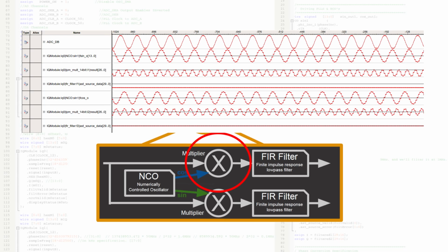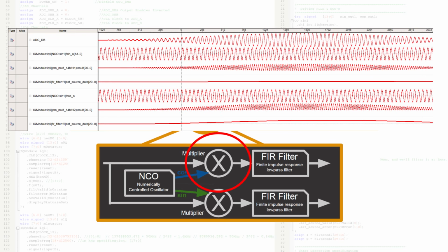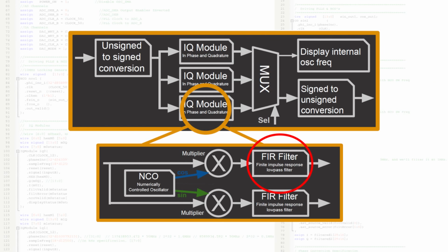The important thing to note here is that the output, both the DC as well as the doubled carrier frequency, still contain the amplitude data of the original input signal. When there's amplitude modulation on top of a DC signal, this just gives you the signal back at some DC offset. This is why this signal is very useful for us, and why we don't care so much about the signal with the double carrier frequency. It's in our interests at this point to filter out this higher frequency that we don't want anymore, and just retain the information on the DC signal.